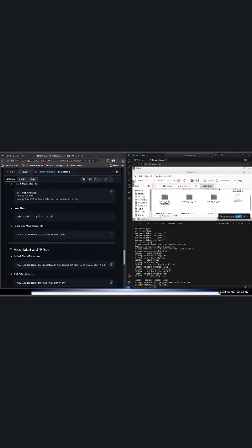With regard to transformations, you have different coordinate frames. For example, in your robot environment, you have an inertial frame, the main frame that denotes motion and positioning for the robot. Generally that is a map frame or something along those lines. And then you also have the frame attached to the robot itself, which is the base frame.